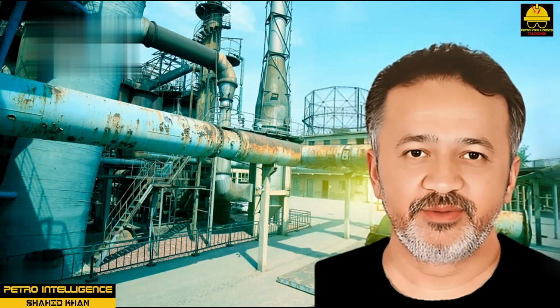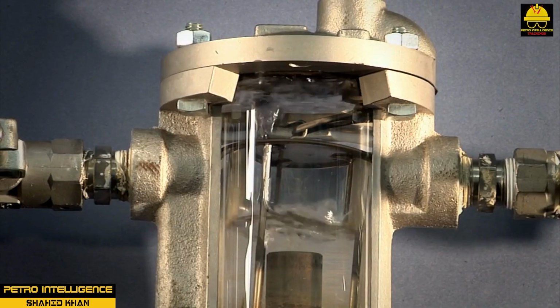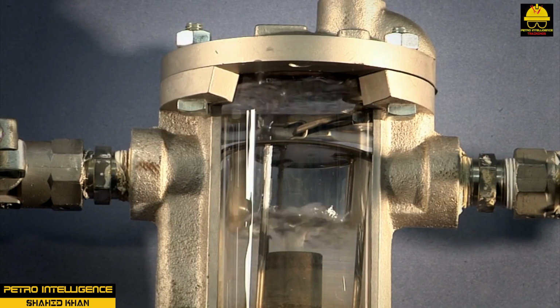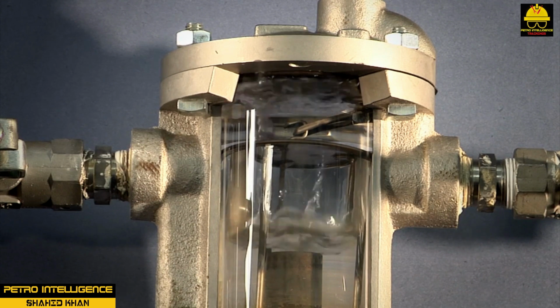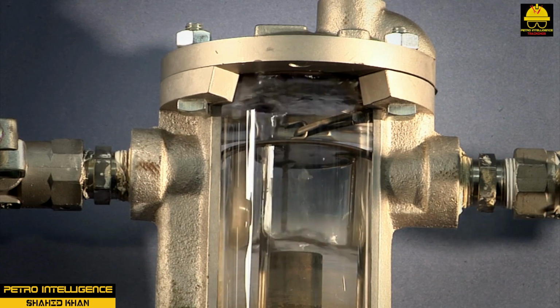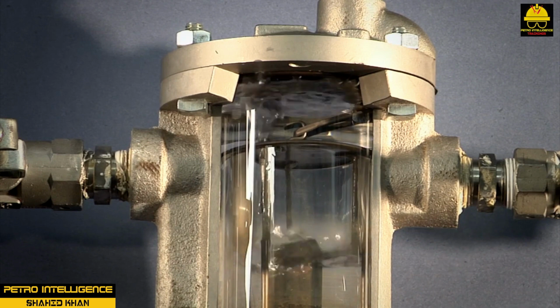Depending on the details of the condensate collection system, the passage of uncondensed steam can be very wasteful in terms of heat energy loss and can cause thermal shock in pipes and systems. Bucket steam traps are used on drip legs and tracing, with moderate heat loads. Operating pressure differential should be specified.